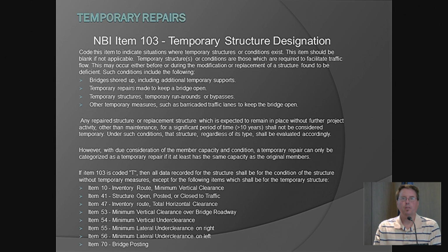So if you have a rotted pile, you come in, you drive a pile right next to it, and you consider that to be a permanent repair, then we recommend that you cut the top 2 feet of that pile next to it off, if you don't pull the pile off at the mud line or whatever, just to show that it's no longer part of what you consider part of the structure.